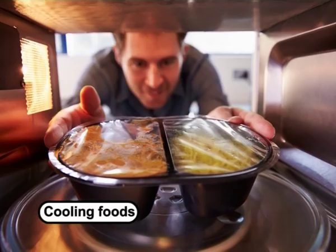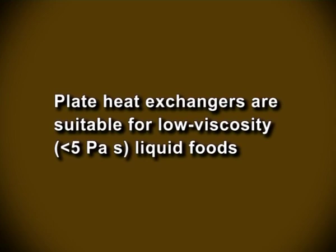These gaskets help to direct the heating or cooling and the product streams into the respective alternate gaps. The direction of the product stream versus the heating or cooling stream can be either parallel flow, that is in the same direction, or counter flow, that is in the opposite direction to each other. Plate heat exchangers are suitable for low viscosity liquid fluids. Low viscosity here means less than 5 Pascal second.